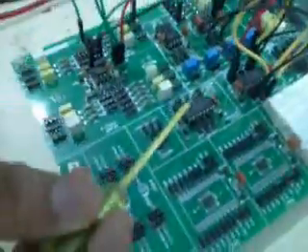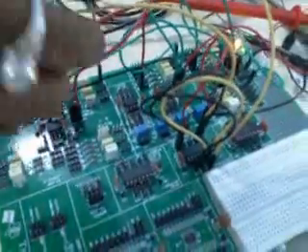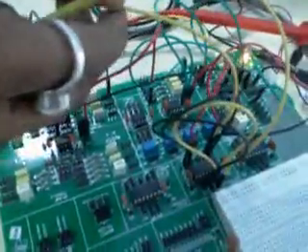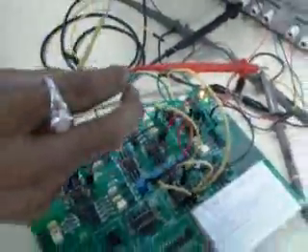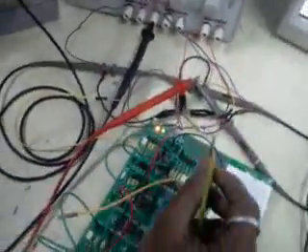Now we can use it with a multiplier. If we insert a multiplier, MPY634KP, there are 3 analog multipliers, and we have taken the second multiplier over here. One input of the multiplier is the band pass filter output, and the other pin is mainly taken as the control voltage.